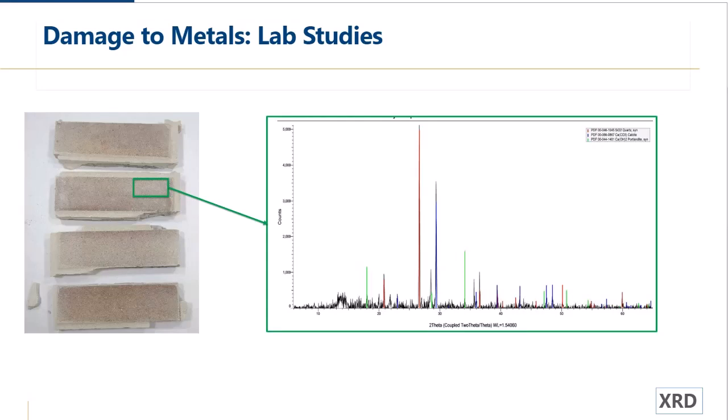And we see some calcium hydroxide, which is not surprising, right? Because that mortar was freshly applied and we know that a Portland cement mortar, like concrete, is going to have calcium hydroxide, which can be leached from the water. We see some calcium carbonate as that calcium hydroxide reacts with carbon dioxide in the air and forms calcium carbonate on the surface. So what we see is really not unexpected. It happens frequently with new Portland cement-based material. It's often called new building bloom.